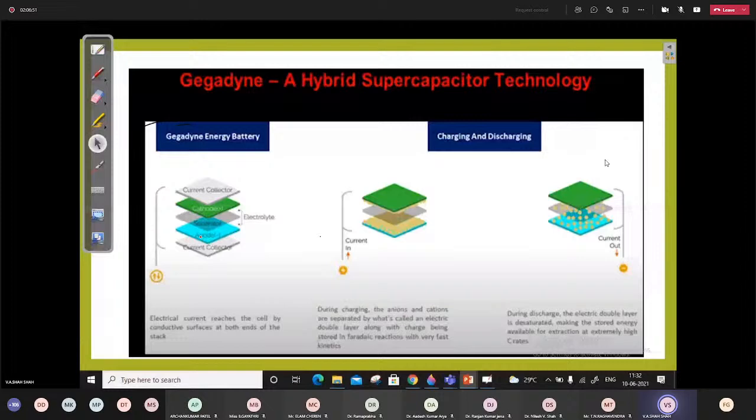Of course, this negative part is nothing but whenever we are reducing speed, the power will be interpreted as a negative power, but it's basically not a negative power. Try to understand, there is always a positive power. If we interpret this as when the speed reduces, whatever power has been demanded by the vehicle, it doesn't demand power, but it can supply that power. So that can be mapped as a negative power. Basically, it is not a negative power.